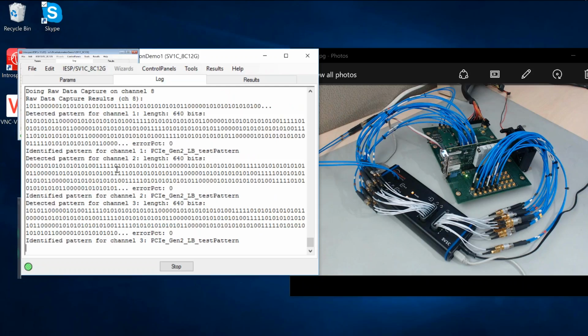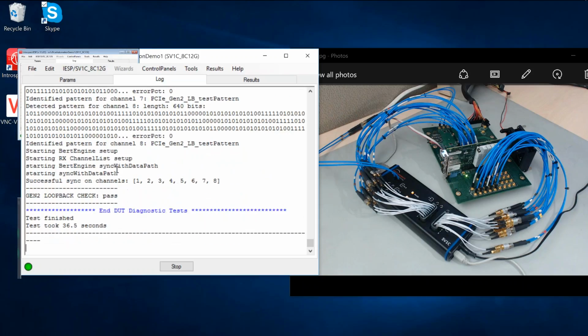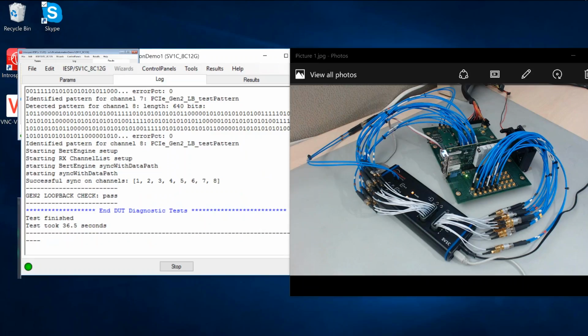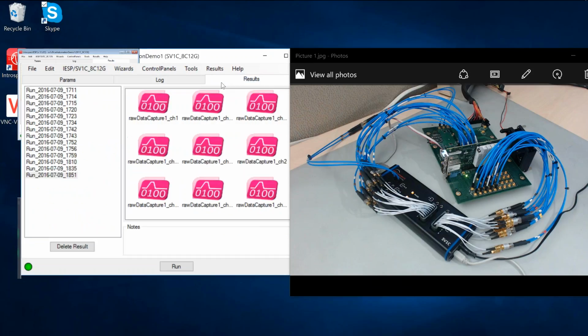And so it's doing this right now as a quick diagnostic tool, and within seconds, as we see here, we're basically able to complete the entire analysis of the capability of the device. So we're seeing that we have 8 lanes that are active on the device, which is what we expect, and that the device is able to toggle to Gen 2 and is able to perform loopback training, which is critical for receiver testing. So this is a device identification step that takes seconds, but within seconds we're able to determine the capability of all lanes.